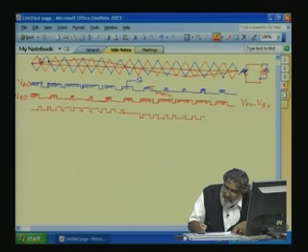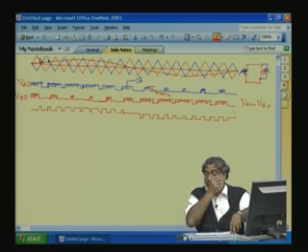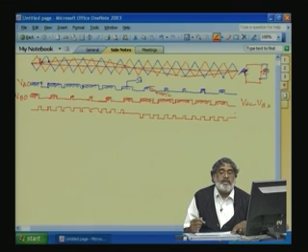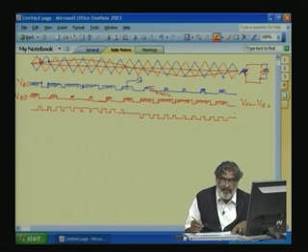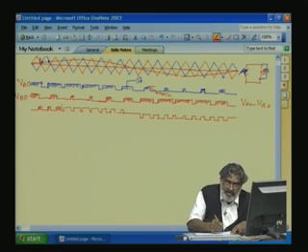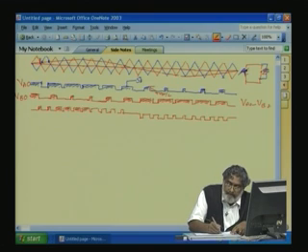If you do the Fourier analysis of this waveform, it will have the fundamental at 2 times the individual leg A or individual leg B. At the same time, it will not contain the harmonics at FC, its sidebands, and 3 FC also. With one converter, the next higher amplitude harmonics happen at the sidebands of 2 FC.